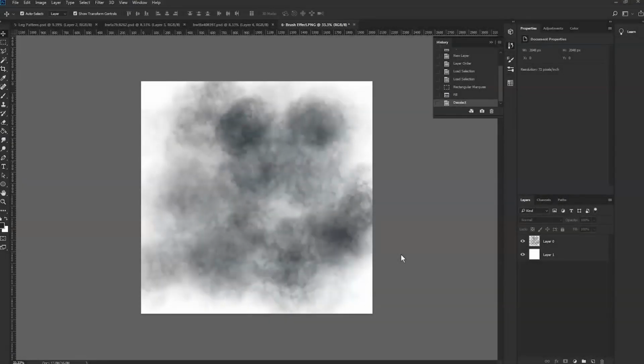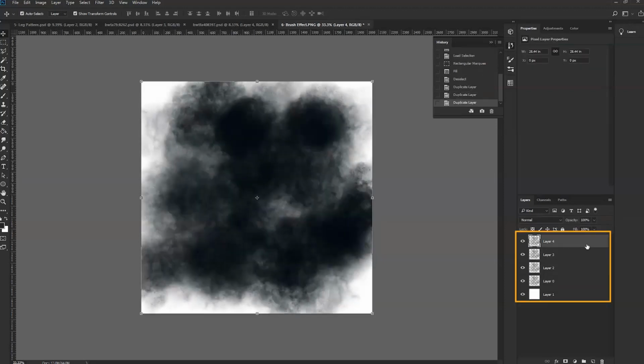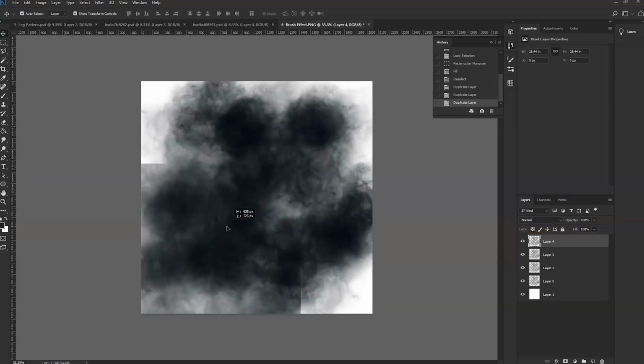The other method is using the all-over print. To create a seamless tile for an all-over print, we first need to use a brush to create an image of the effect, like this, in Photoshop. If you do not have suitable brushes, you can also create these images within other raster-based software, like Procreate, and add them into V-Stitcher. The key to creating a seamless tile is to ensure the four corners of an image match. So we duplicate the layers 3 times and drag each image onto the 4 corners of the canvas.